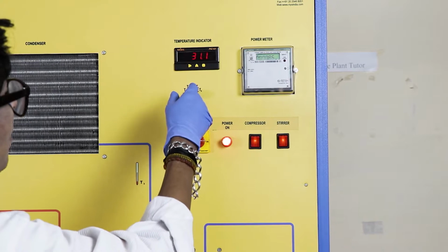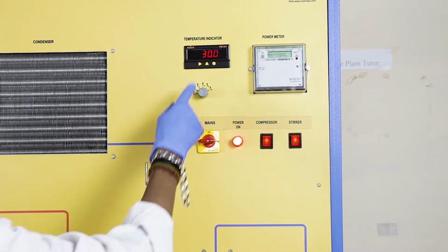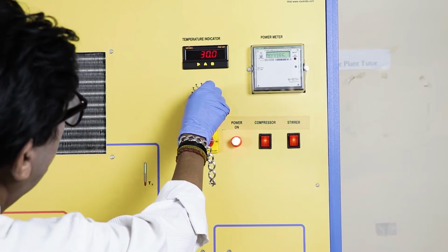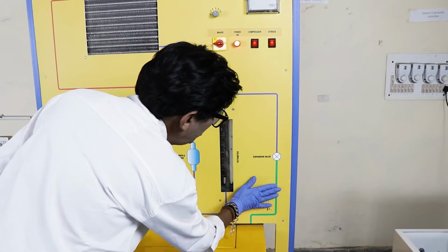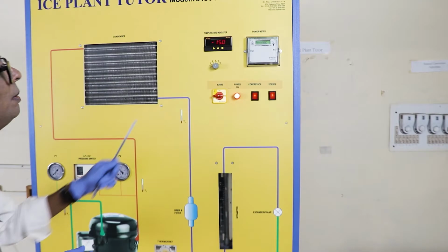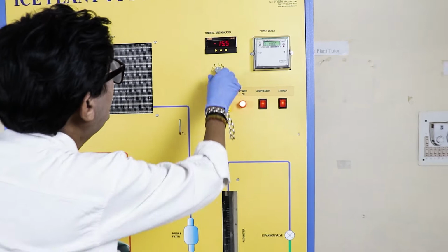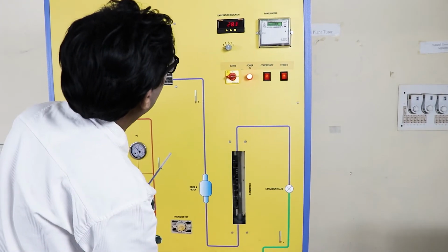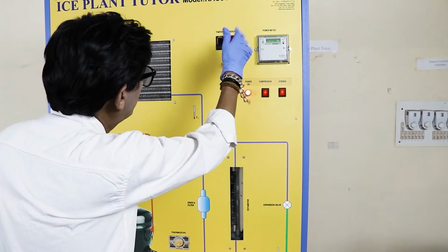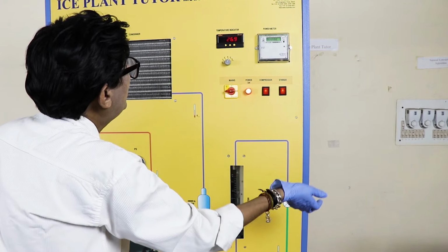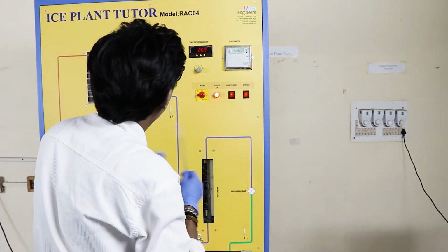We'll make it run for some time. This is T3. T3 is the temperature after the condensation process, which is 30.0. And then we have T4, which is the temperature after the expansion. It should be lesser. Look at this. This is coming to be minus 15.1. This is quite less here. And if you find T5, which is the temperature of the brine solution, which is dropping, it was about 20 and is continuously dropping. Maybe it's presently 26, but after some time this will drop. So these are all 5 temperature values.